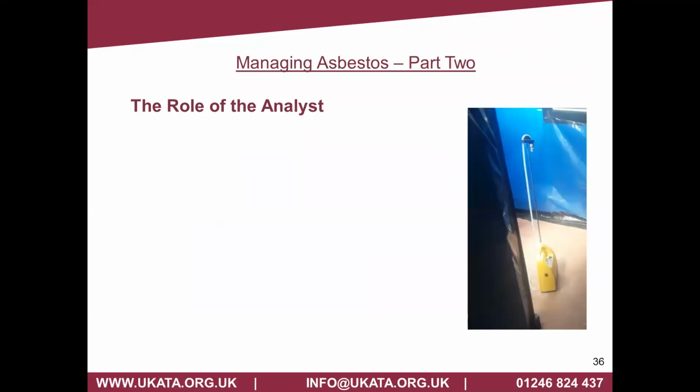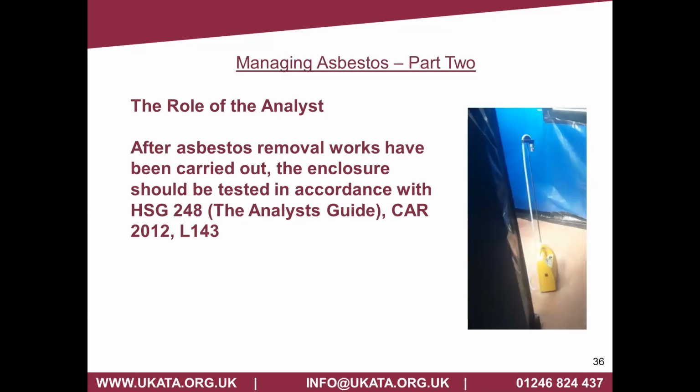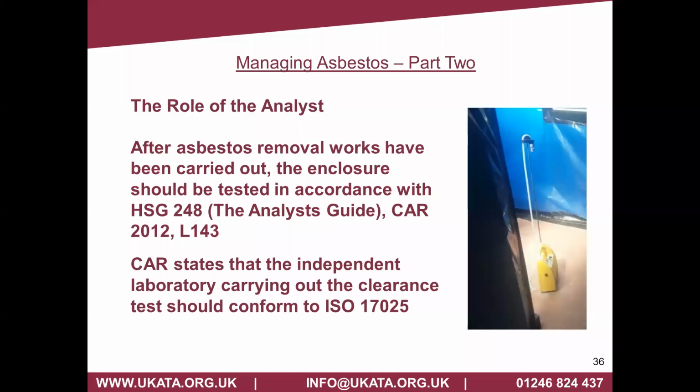Now, let's assume the licensed contractor has done the job inside the enclosure. They've finished. How do we know they've done it properly? One of the requirements of the Control of Asbestos Regulations is that they must engage a UKATA accredited analyst to undertake the certificate of reoccupation. This is done at the end of the job. This will be done by the analyst. I'll show you the certificate of reoccupation shortly, but they must be independent of the contractor.